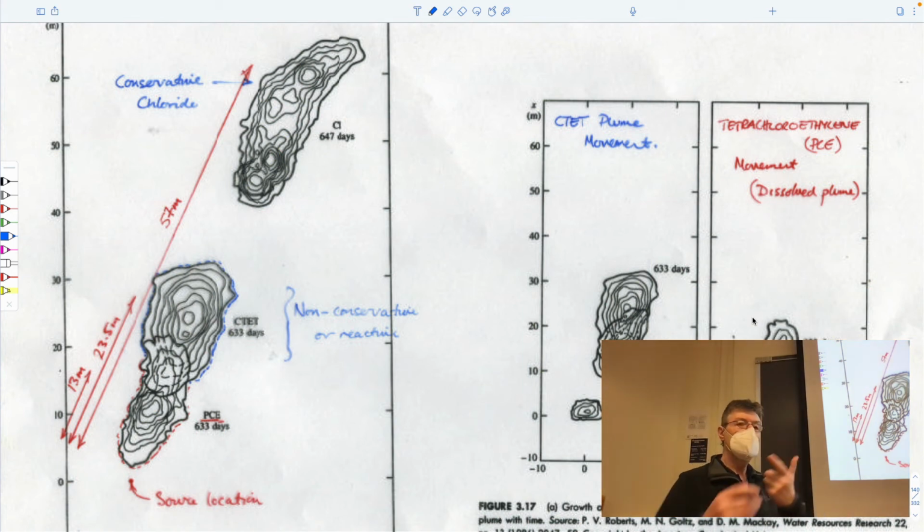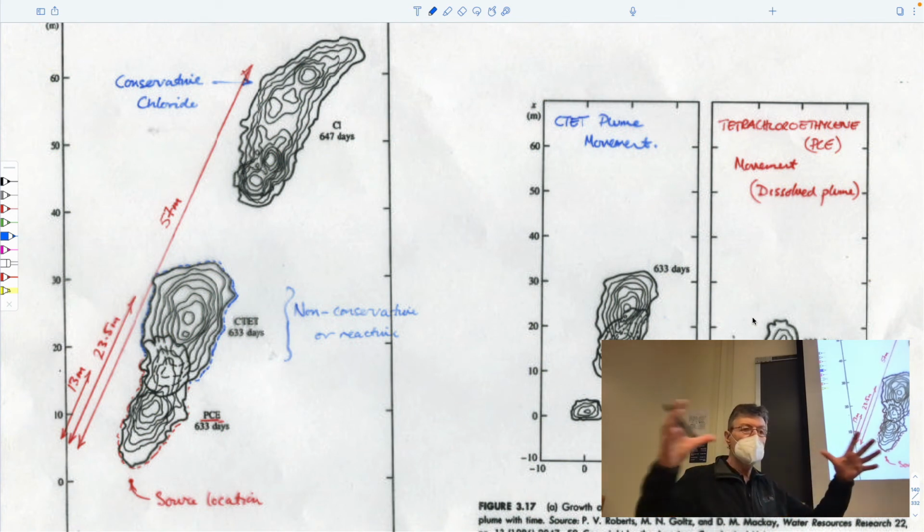And you remember last time we talked about 3 experiments. One was in a core. We said that's no good because the core is not a very representative sample of the aquifer and doesn't include all the heterogeneity, which is the essence of the dispersion, which occurs at much larger scales. So core is no good for us. We talked about single well pump in and pump back out tests and twin well pump in back out tests. And we decided that those are better because they're a larger volume.